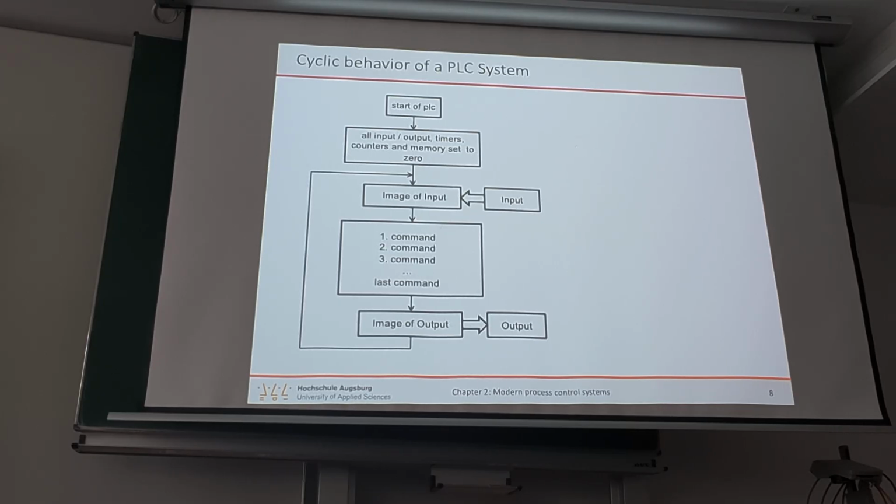But for example, in the oil and gas industry, if you have temperature control of a big storage, it's okay. That is a cycle time of 15 minutes or whatever. That's okay because it does not change very fast. So it depends a bit on the application, but typical in factory automation is between 1 and 10 milliseconds.